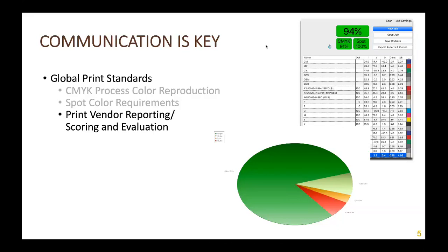We do an initial press run before we even qualify them as an okay vendor for us to use. We go on site, we run a print trial with them. It doesn't even need to be our art necessarily, but if they're running a job, I want to see that their press people have a proof on site, that they understand what they need to do to get what is coming off the printer to match to what's on the proof, and that there's a good visual match as well as a good numerical value match using a spectro and.